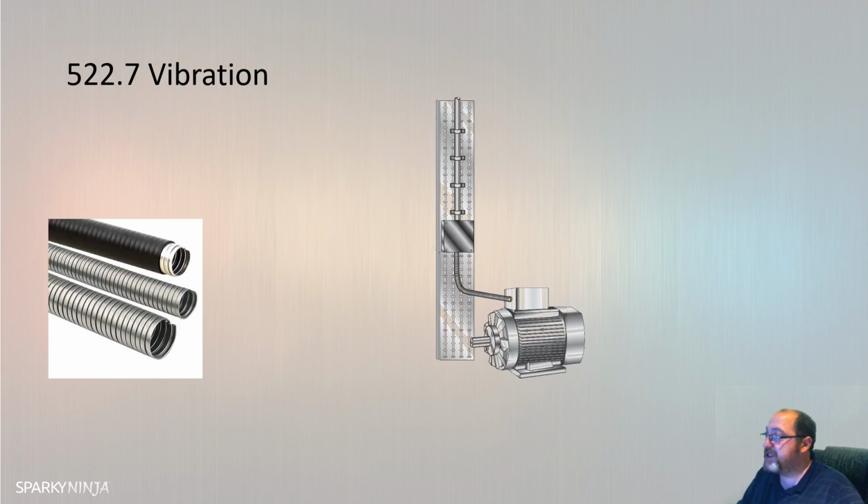So, flexible conduit is used mainly for this purpose. From the fixed wiring to the motor. Just there, not the whole thing, just there, really. And it's then saying that if we're going to have luminaires or anything else that might be subjected to movement or vibration, then they will be of a flexible type instead of a solid type.